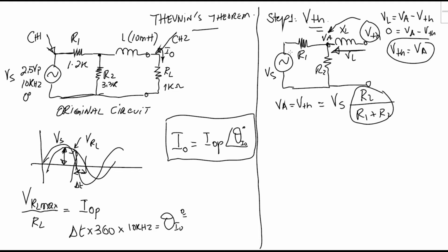So this voltage drop will be deducted from Vmax of this Vs, giving our Vmax across this resistor, or at this node Va. Okay, so once you do the plot, we keep connecting our channel 1 here and channel 2 at this point here.